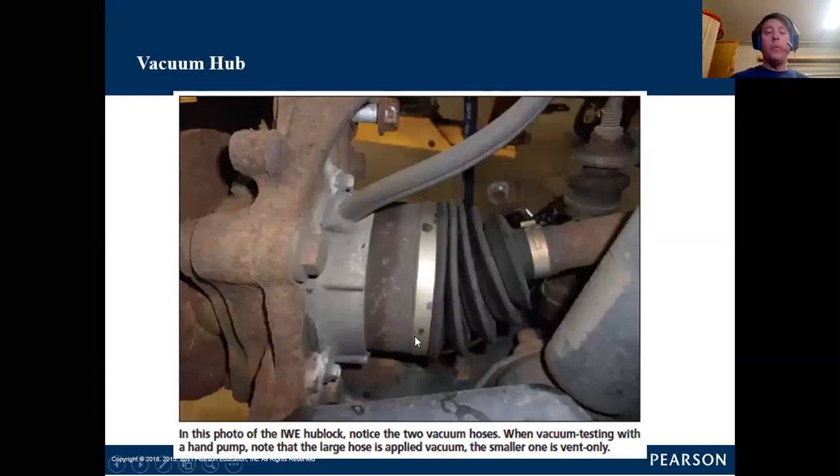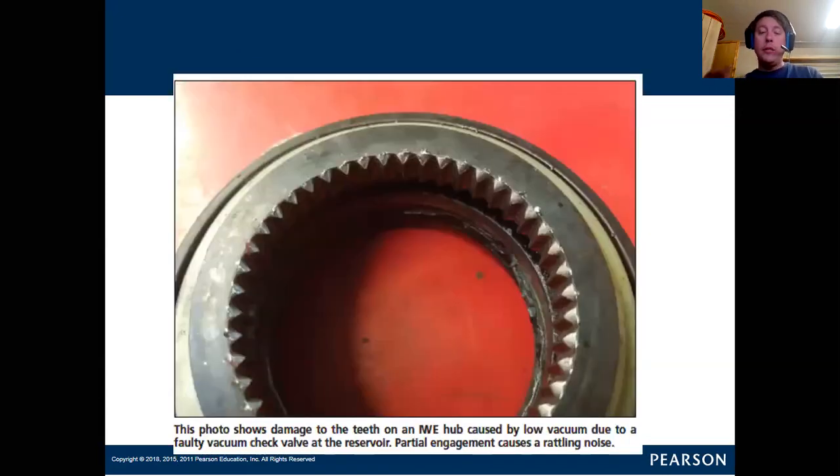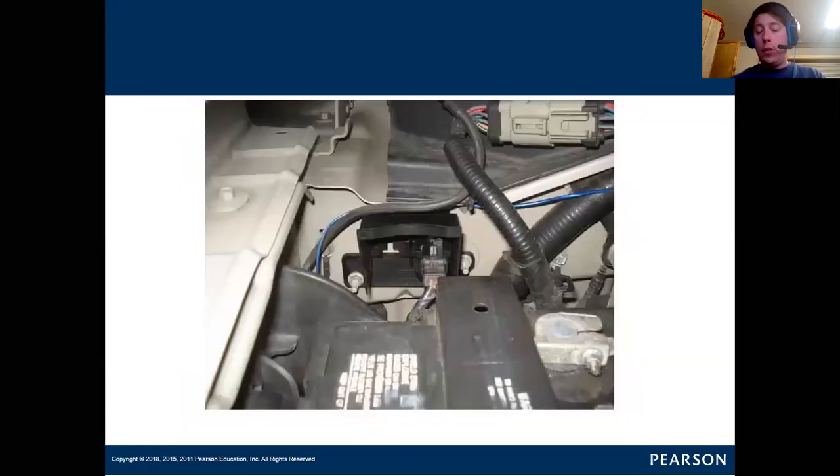So there, I went the wrong way. The CV axle also has a mating gear set spline that in one direction, when that hub moves, locks it to the actual wheel hub where the tire is bolted on. When you want to disengage it, it pushes it away, so the wheel spins freely and the CV axle just sits there, not engaged. So the CV axle stops spinning when it's disengaged. It begins to spin when that hub slides over and engages in the spline teeth, the grooves.